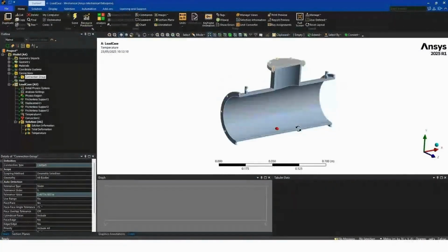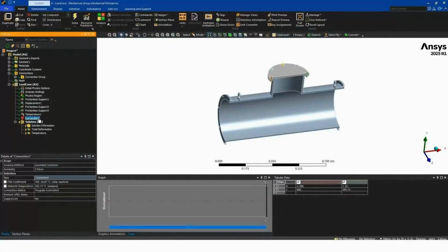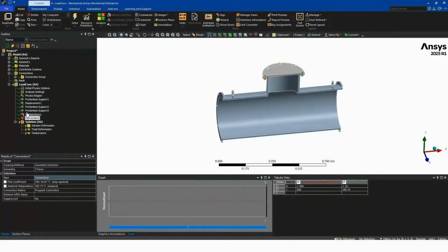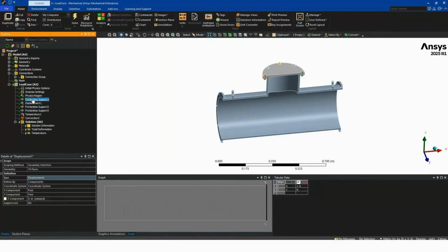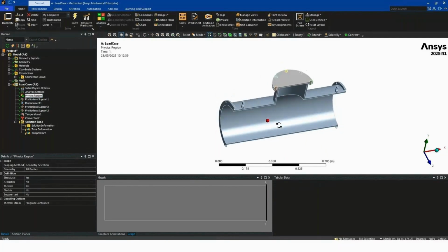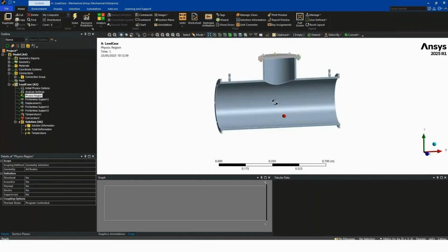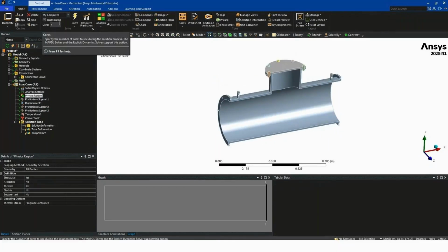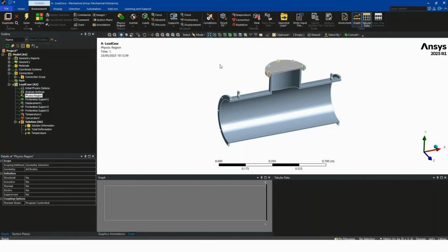And you can see that we've got our model set up as we set it up in Creo Ansys with all of our boundary conditions. And this is going to allow us to use all of the functionality within Ansys Mechanical to do whatever we might need to do outside of Creo Ansys. For example, utilizing the HPC capabilities, or just using some of these more advanced boundary conditions.